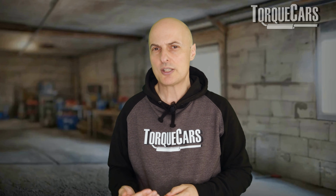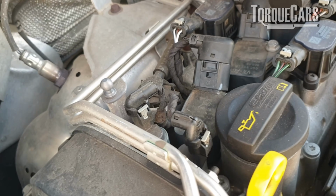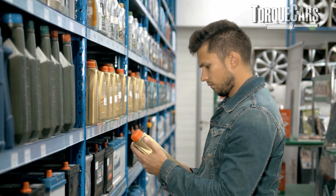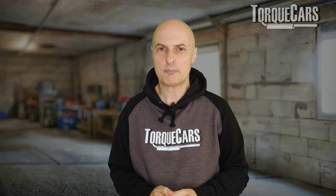And again, that's something that's going to manifest itself at higher RPMs, whereas the engine can cope admirably well at lower RPM. Oil condition has quite a major bearing on the VVT, or the variable valve timing systems. They're quite sensitive to wear and tear caused by the wrong grade of oil or insufficient oil pressure. Do check the oil, and a lot of these faults will manifest themselves straight after an oil change, particularly where the wrong grade of oil has been used.